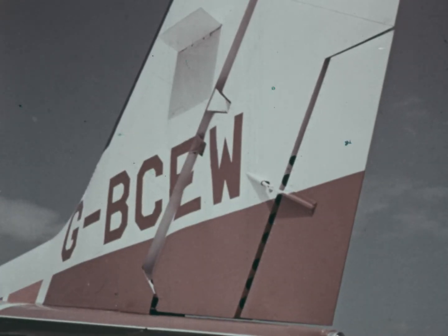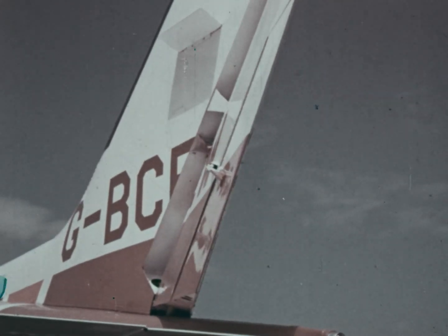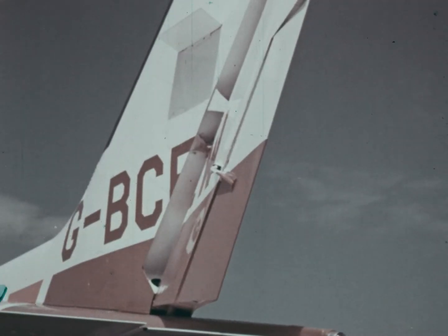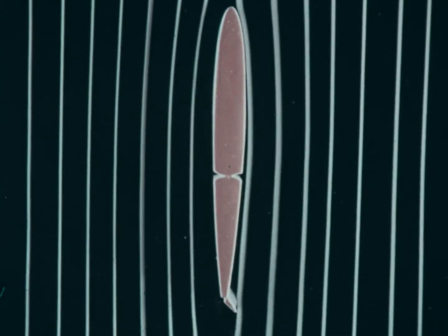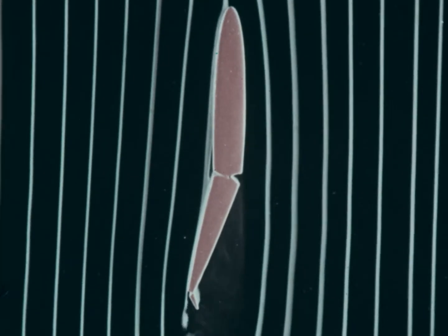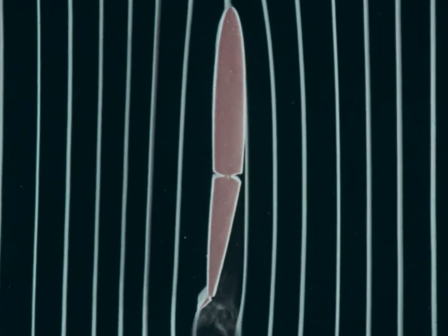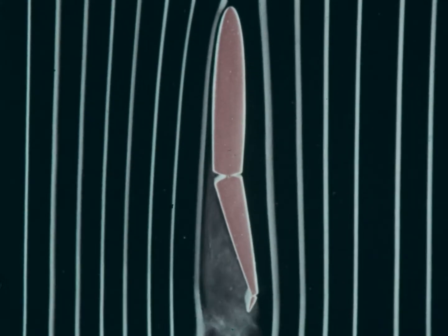The way in which a displaced control surface can be held in position against a considerable aerodynamic force is by means of trim tabs. These are auxiliary surfaces fitted to the trailing edge of a main control surface and working in the opposite sense. Thus, a rudder trim tab applied to the right will hold the rudder to the left, and vice versa. Trim tabs enable the pilot to correct and hold any normal variation in the trim of the airplane without having to hold the control force physically.